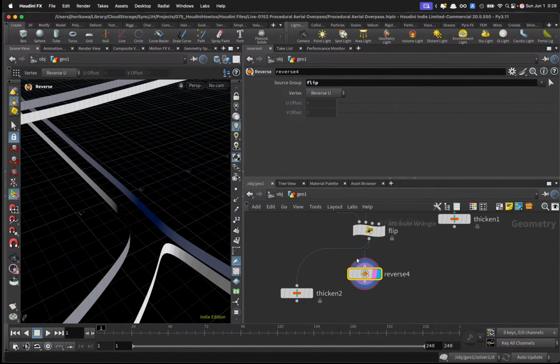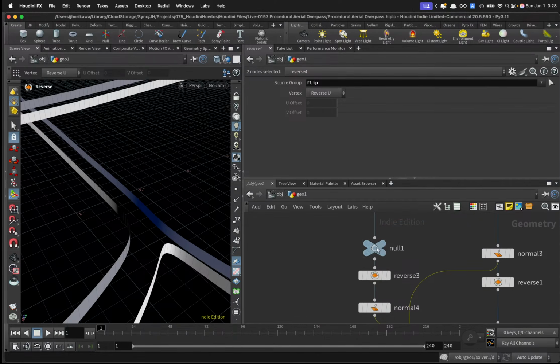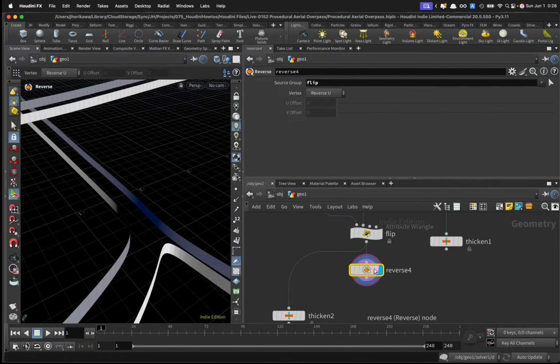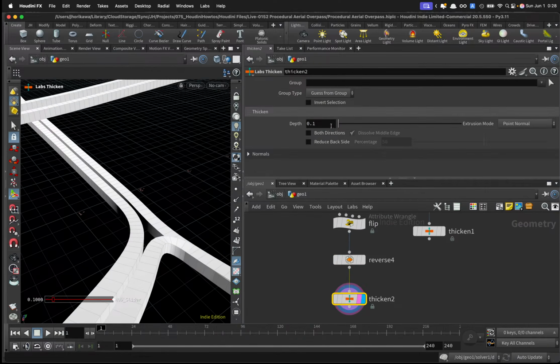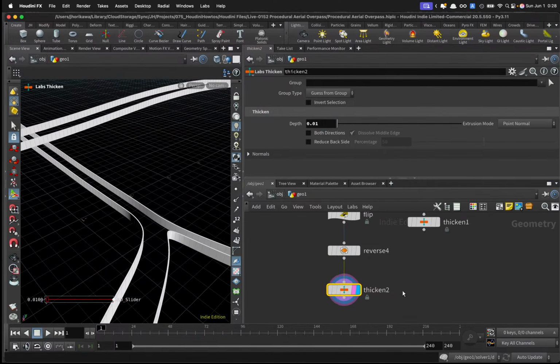Okay, so that seems to work. Now you can remove the test case, or just in case, I'll keep it. Okay. Now after this, you can just apply thickness to the wall, the fence wall, with some small thickness, and use it as a fence.